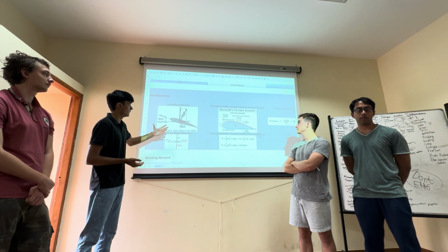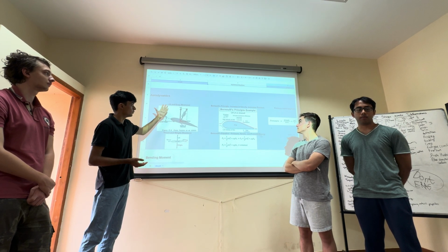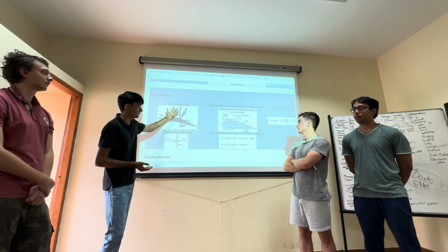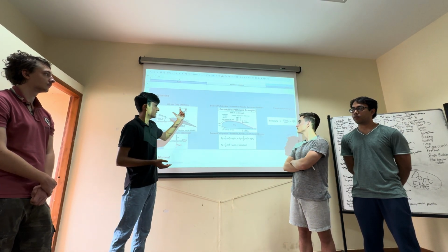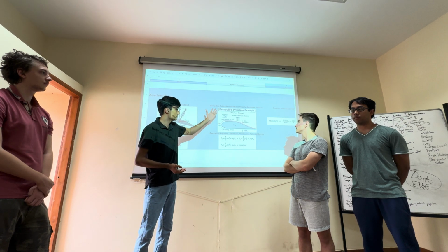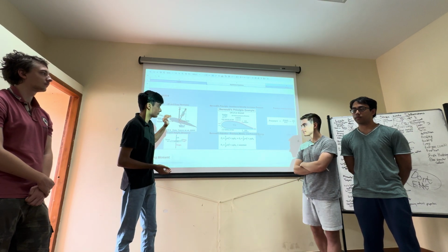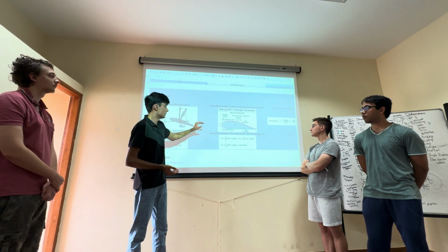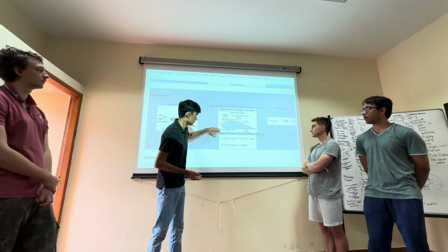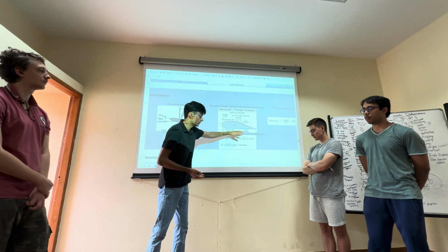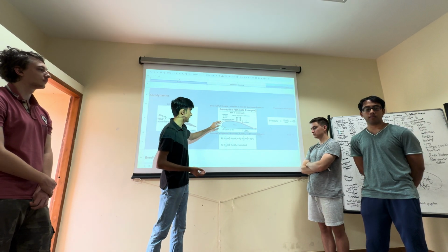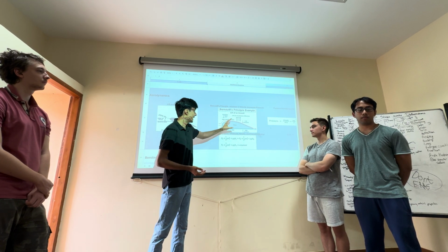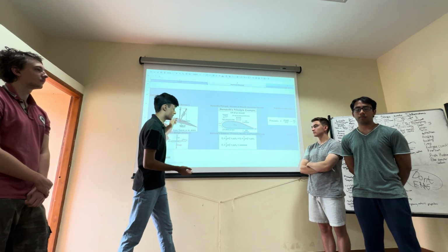Now, let's take a look at how these forces are created. If we take a look at lift here, we'll find that that's really related to Bernoulli's principle, which is as the velocity of a fluid increases, the pressure decreases, right? So we see as there's lower velocity at the bottom of the wing, there's higher pressure, and high velocity at the top of a wing, so there's low pressure, and that dynamic creates that lift that we were talking about